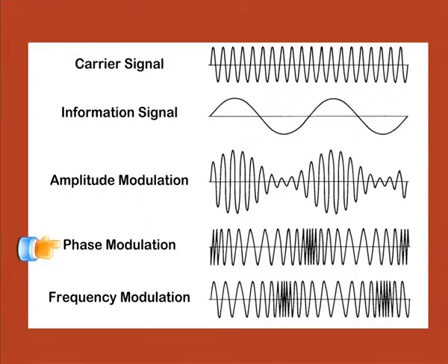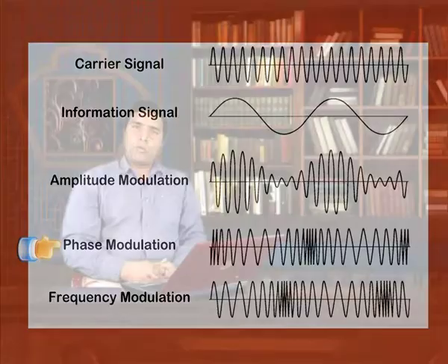In the fourth waveform, what we see is that the frequency output of the carrier signal is varying with the information signal. Though it is a phase modulation, the ultimate effect we observe on the carrier is the frequency variation. This will be explained later in the topic of phase modulation, that why when we vary the phase of the carrier signal, the observed frequency is also changing.